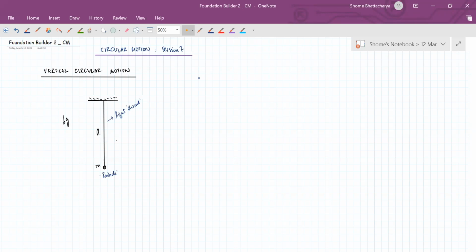So there is some margin for error within that also, because different types of tires will have different coefficients of friction, and also depending on the temperature of the road surface and weather conditions. There are all these other factors which also determine the limiting values. So the maximum specified velocity for negotiating a turn on a highway is taken with all these factors into consideration. Okay, so hope that makes it clear. But banking angle is a part of the consideration in that, of course.